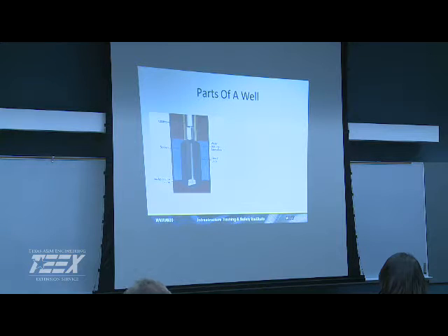One of the things that they do to help with your well production is they'll take a reaming device after they drill down. They'll put it down in there, and as it spins, it actually has blades that open up. It'll over-ream the well for you down there, whatever your screening area is going to be. And then they'll put in a gravel pack. And the gravel pack is to help separate the natural aquifer materials from your well screen. And so as you're pulling, you're going to pull a nice even flow of water in rather than sucking up materials next to your screen and then you got to purge it and things like that.